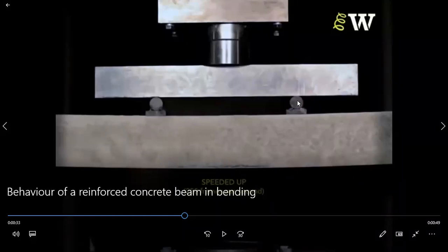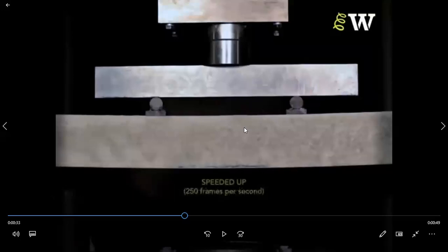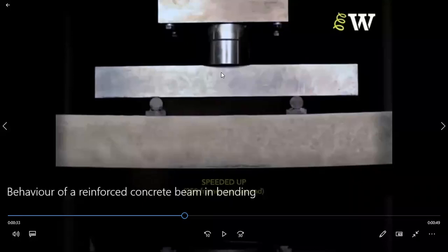This is 1 point load and this is the other point load. Over this, there is a beam which is again loaded with 1 point load here. So in total, how many points are there? 3 points. Okay, that means the load W is dividing into W by 2 and W by 2. So this is called 3 point loading. Can anyone describe why the loading is in this way? Why can't it be just a single point load? Why is this W load distributed to W by 2 and W by 2 to calculate the pure bending?